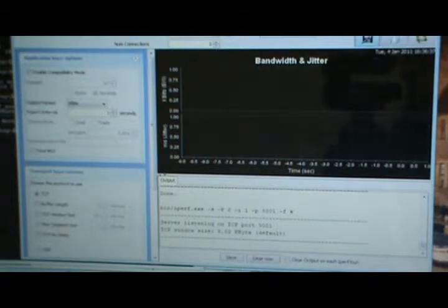On the server side, run the command iperf -s -i1, or using the JPerf utility you can run JPerf as shown on the screen. On the client side, run the command ./iperf_arm -c 10.0.0.2 -i1 -t30, which uses the server-side IP address. Now you see that the throughput is being recorded, and this is how the iPerf utility works on the ARM processor.